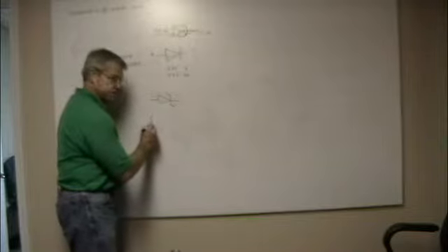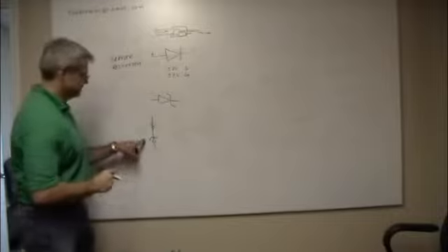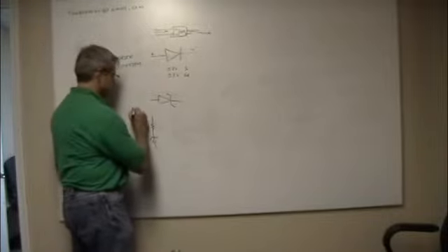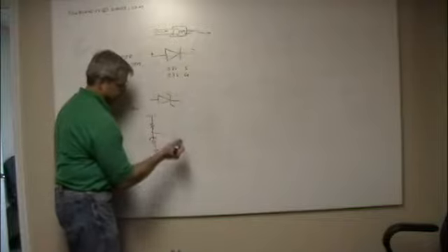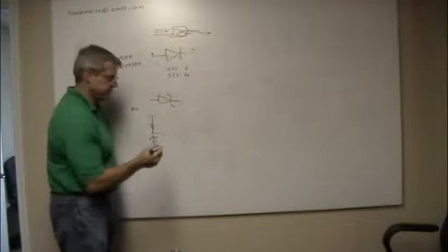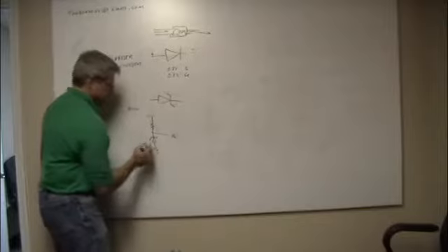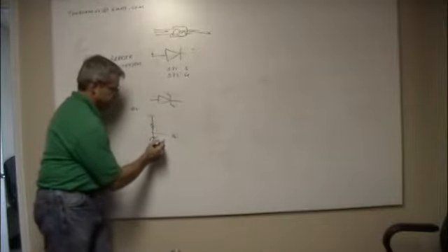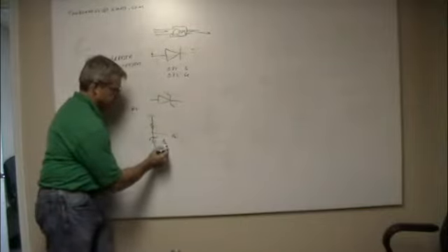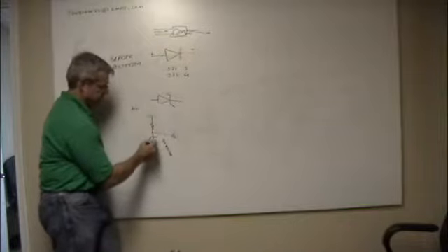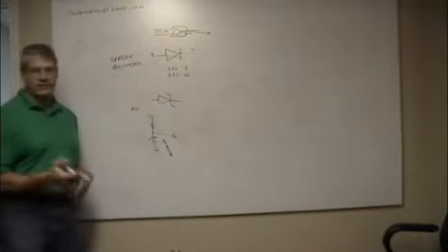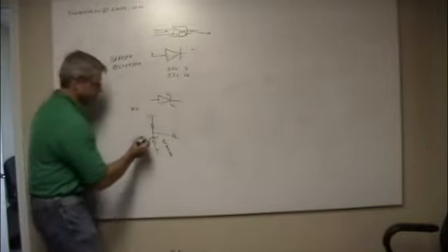So this is a ballast resistor, and you have to look at the data sheet and you say, oh, I've got 10 volts here, but I want, I don't know, some reference that's like maybe 3 volts out here. So you'll choose a 3-volt Zener, and they'll have a current rating that is like, I don't know, 5 milliamps, something like that.